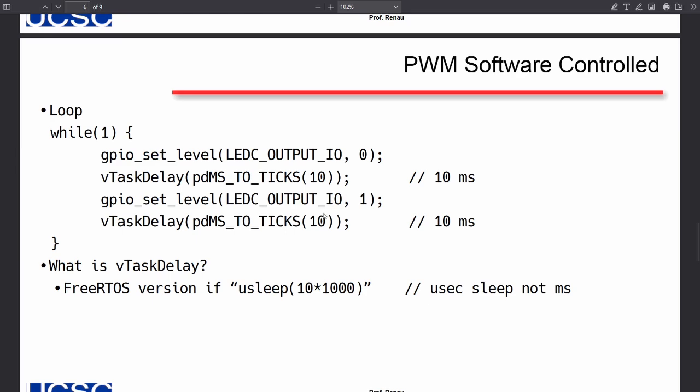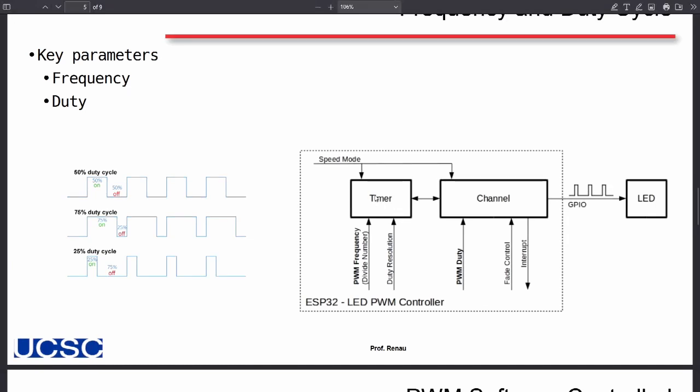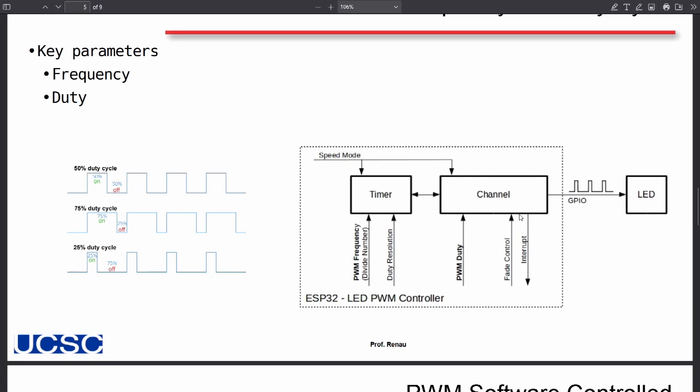Okay. What instead you would do is you would take advantage of the internal hardware that goes into ESPs. Okay, anyone remember Verilog? Anyone in here who has written some sort of counter in Verilog? Okay, good. That is actually exactly what an ESP's internal PWM hardware is. You have some timer, and it's just a counter, and it will count up from 0 to some sort of reset value. It'll count up, then reset, and count up, and reset.